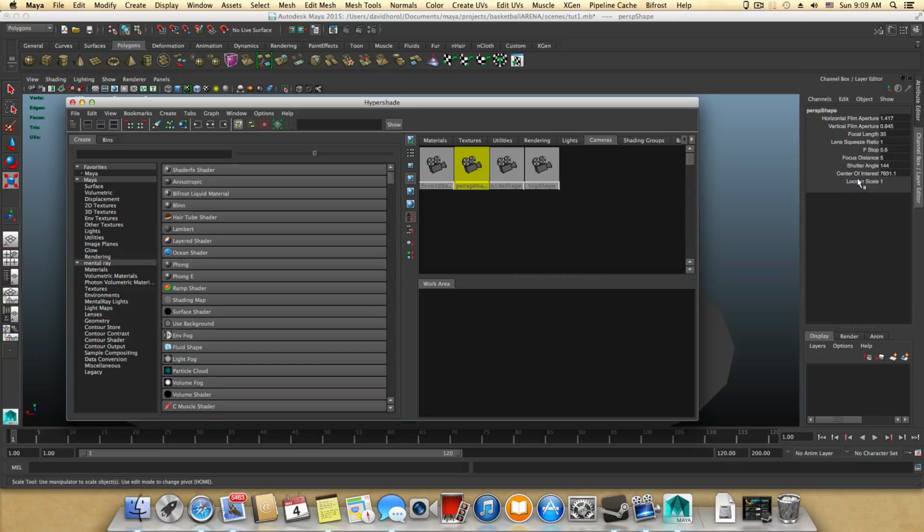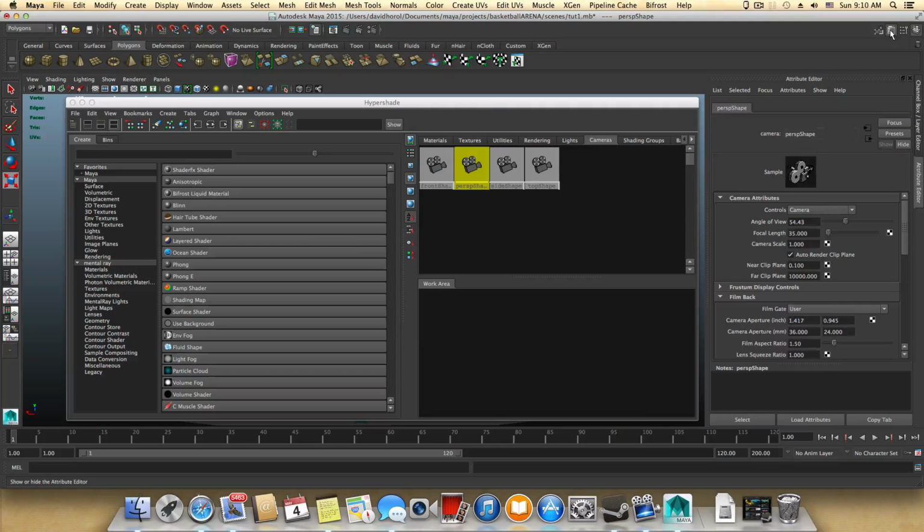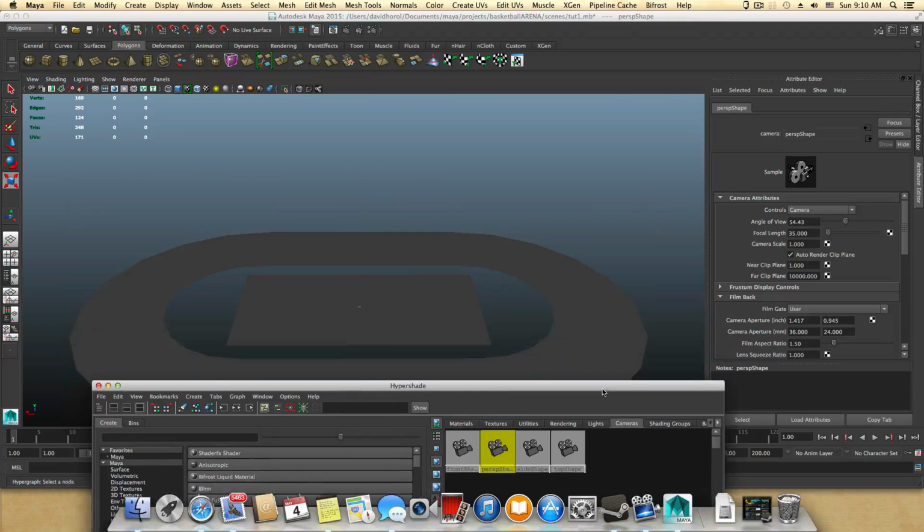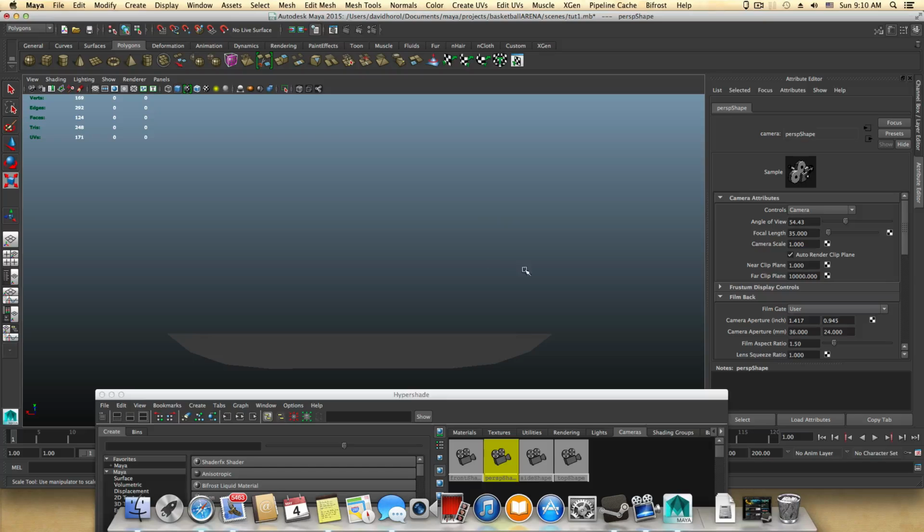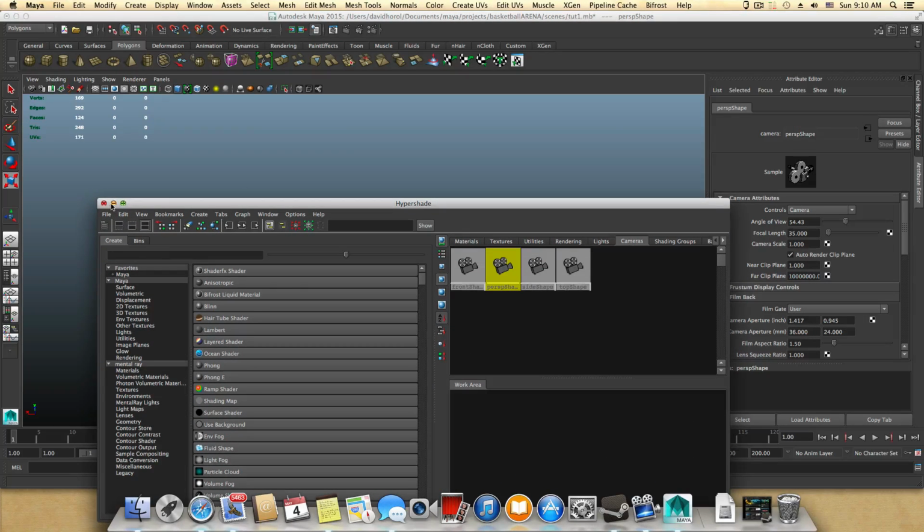This will open this thing here. So with that selected and this opened, click on the Attribute Editor button, and where it says Near Clip Plane, type in 1, okay? Now I will show you what's happened. Let's say we are like that, and yeah, 1 should serve us well. Bring this up a little bit, okay? For the Far Clip Plane, add some more zeros so you can see more of the scene, and you can close this.